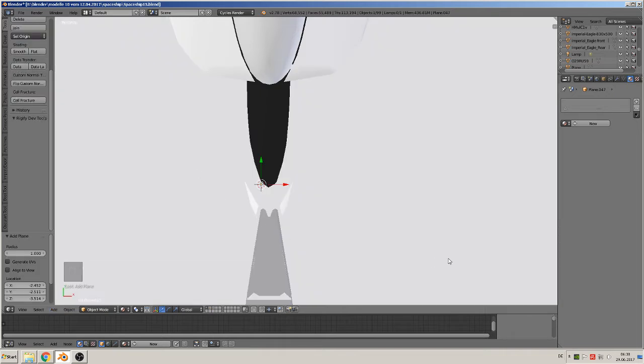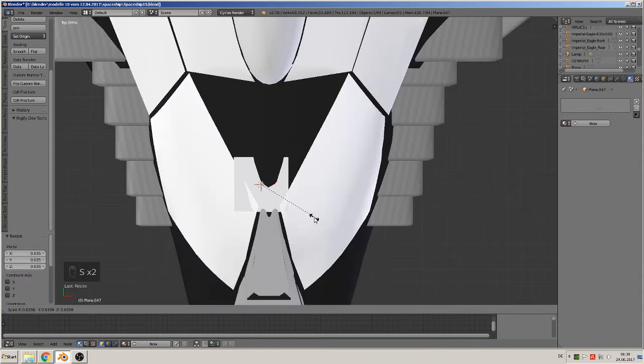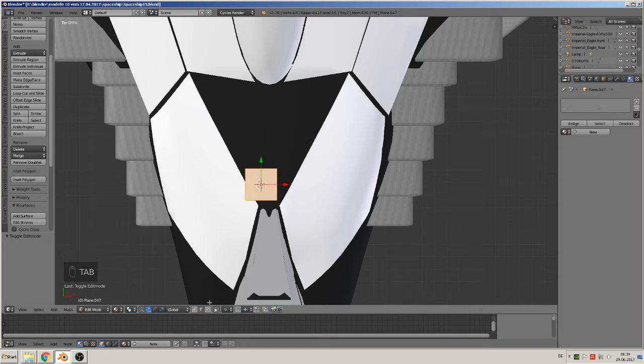Scale down. Grab set to bring it on top. Edit mode, word select, and delete 3. Get 1, grabbing, we make here, extrude to that point, then here, and then straight up there, and close that up. Little tweak. Good.